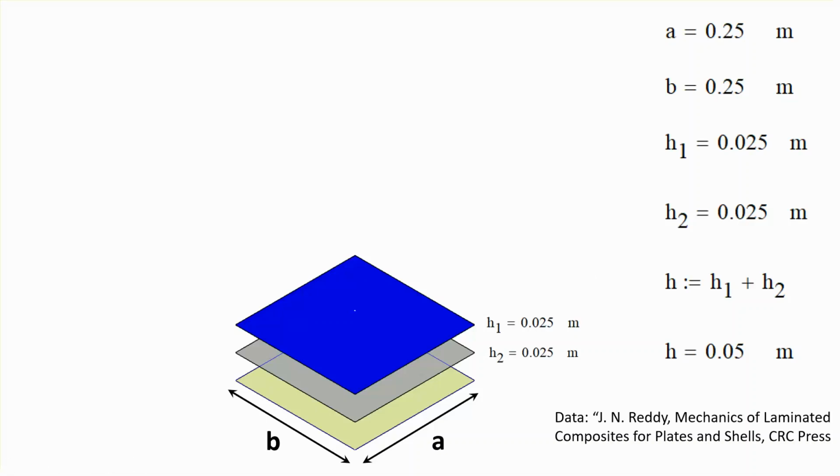Now, this is really not a good set of numbers that they have picked, because generally speaking, the thickness must be smaller compared to a dimension. But as far as comparison is concerned, because he's solving it partly analytically, it really doesn't matter. So we're going to pretend that the classical laminate theory that is used, or a variation of it that's used in the software CATIA, is applicable, in spite of the fact that this is a relatively thick laminate compared to the overall dimension.